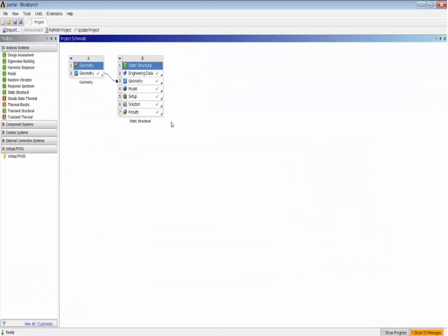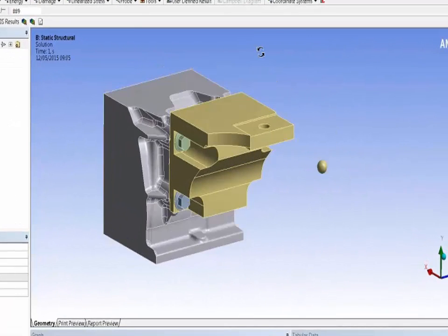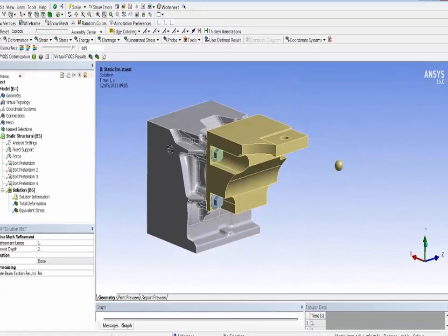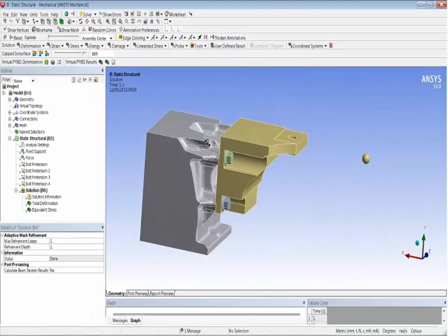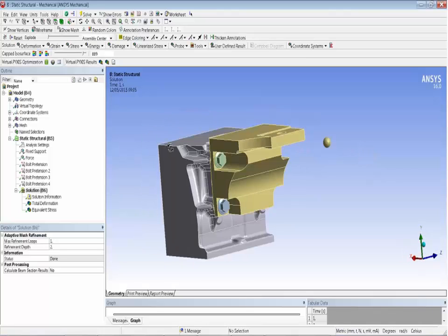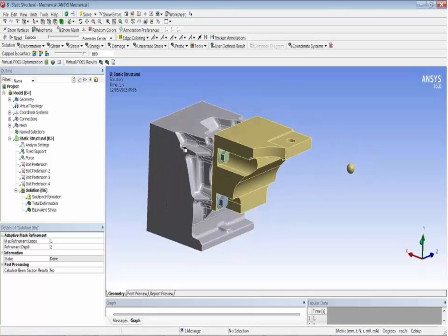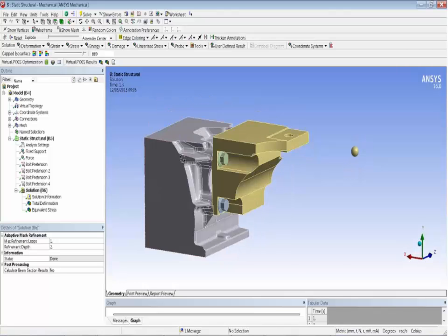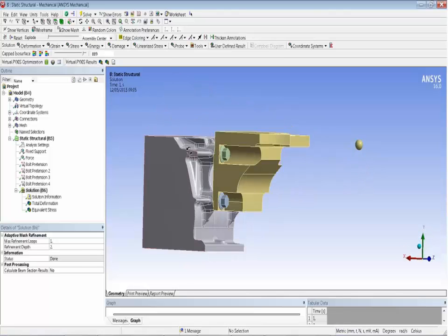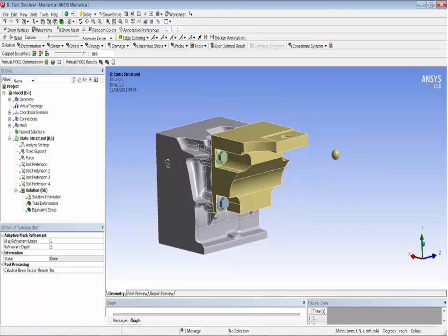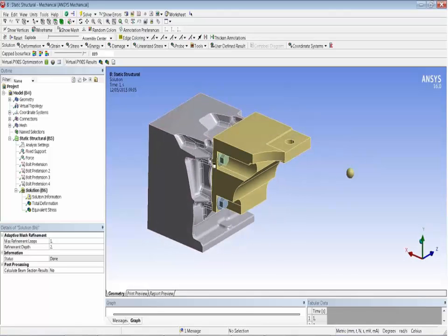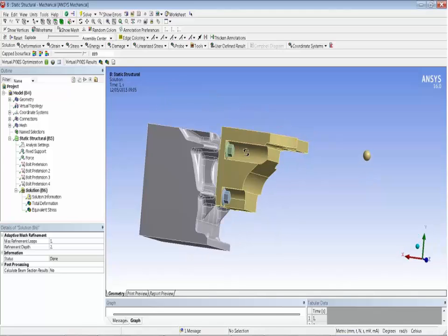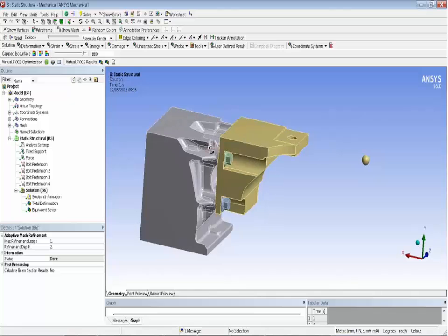So here is the first part of the presentation, the workshop. I have a real model. This is an engine support, as you can see here, with some components. There is the engine block here, which is just a part of it. It's more generic, but the idea is to have the bolt pretension load, and we can also have some stiffness here.